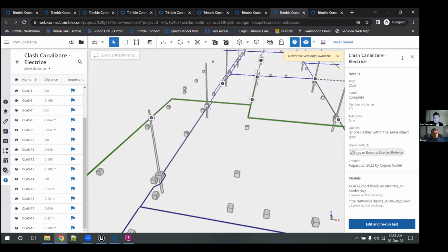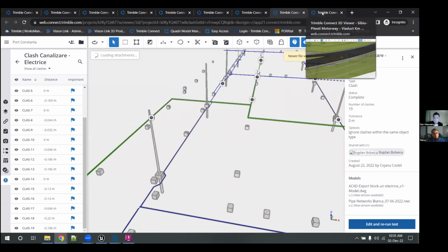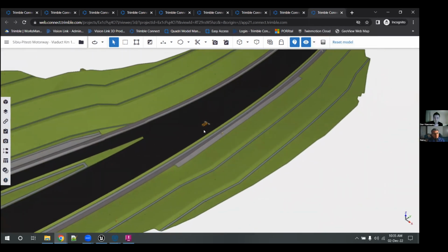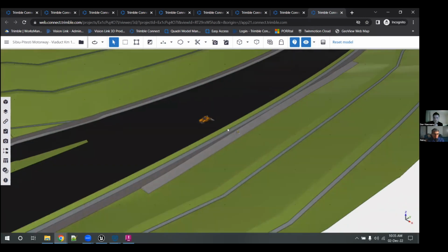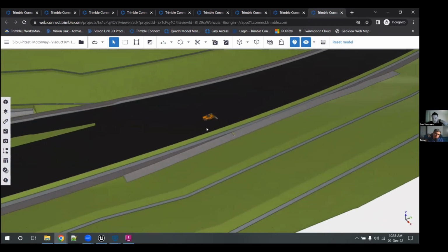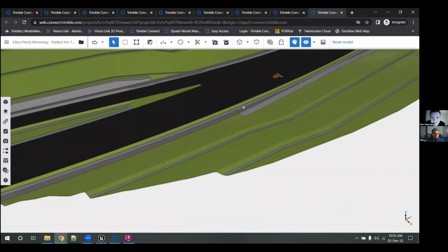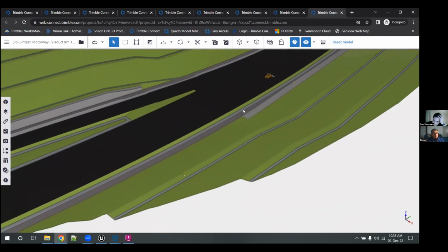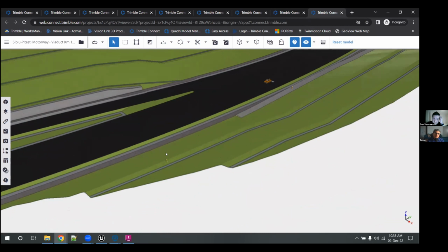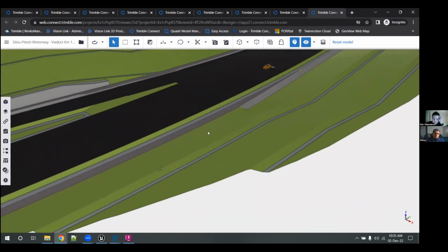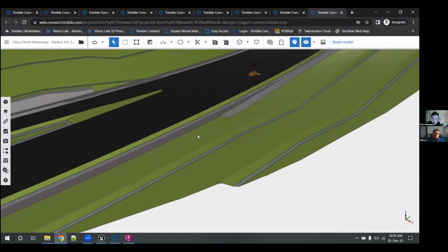Another weird use case, something you don't see very much about for Trimble Connect, would be this. Visualization is one thing, but what I did here in this view: at one point, my department had a presentation for the whole company regarding 3D paving. So taking the 3D models and putting them in the paver and also in the total station to be able to pave without sticks on site.